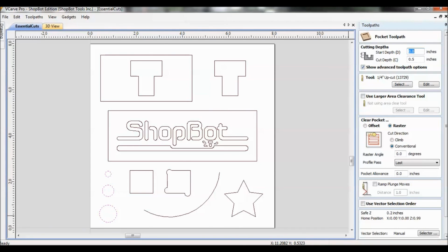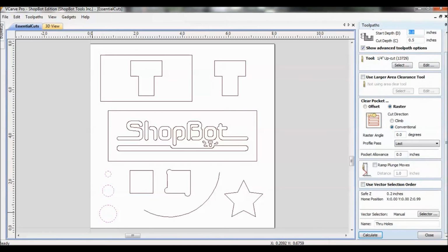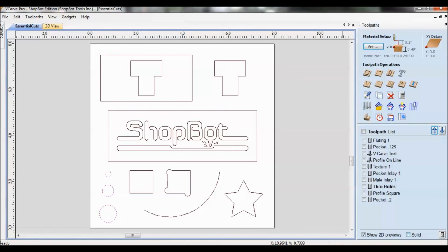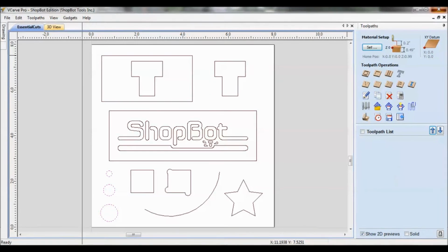And the other thing you need to think about too is what if somebody says, why not do a profile? Well, that could leave a little bit of profile inside the line. That could leave a little bit of scrap right here, and that could be enough scrap that would come up and break your bit. So that's one bit used to pocket all 3 of those out.